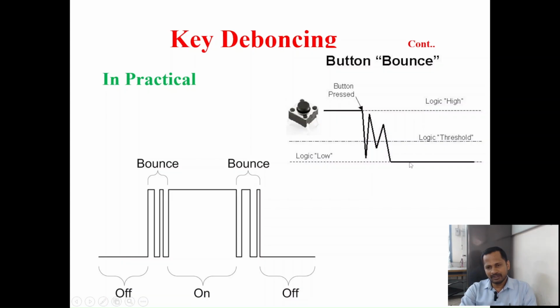Whenever you operate your electrical appliances like mixie, grinder, washing machine or iron box, sometimes you may get a spark while switching on your devices. Because of that internal elastic property, the contact goes high, low, high, low. It means that we are connecting, disconnecting, connecting, disconnecting, so that we get the spark.